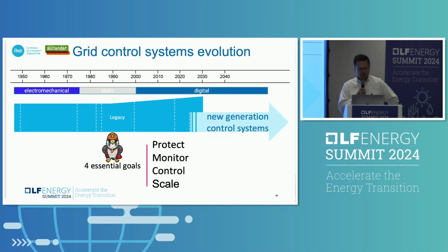So they're looking at their next generation control system, but what they're really doing here is they're having older substations using IEC104, using TASE2, using HNZ. These are different protocols used in different substation infrastructure, and they have a new EMS system, and they need the ability to have the older protocols and the newer protocols cooperate, as well as the set point controls coming back from their EMS. And so Fledge takes care of the pipeline both directions as a multi-protocol gateway.